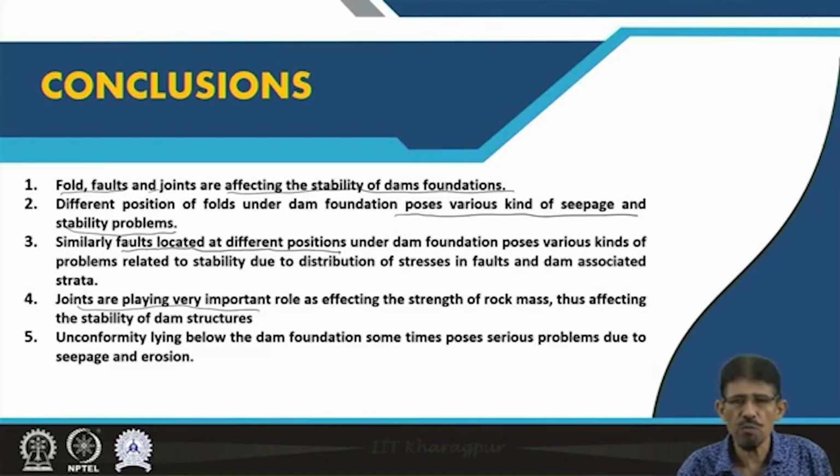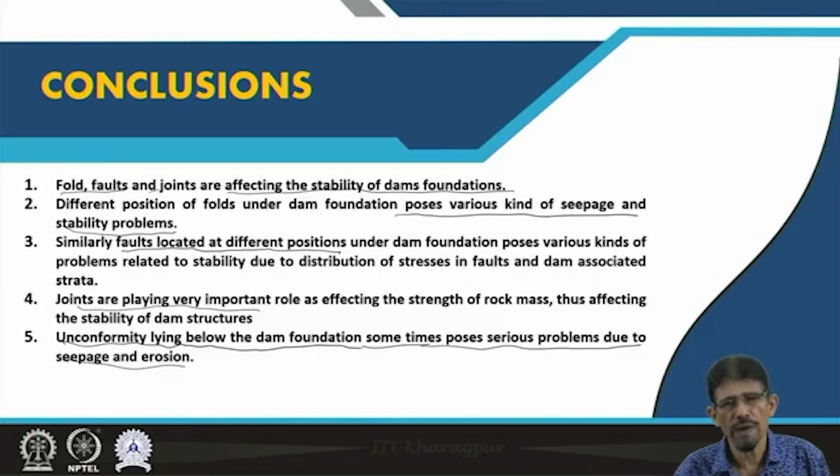The strata has to bear the load of the dam structure as well as the resultant effect caused by hydrostatic, hydrodynamic, wave pressure, silt pressure, and pressure due to ice formation, etc. Unconformities lying below the dam foundation sometimes pose serious problems due to seepage and erosion caused by the presence of interfaces between the overlying older and younger rocks, and it also depends on the orientation and location of such interfaces, how close to the dam or how far from the dam.